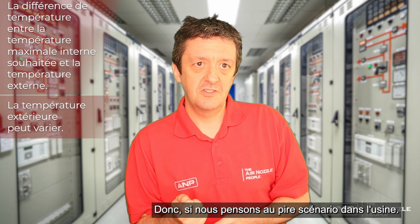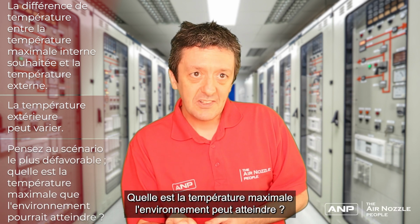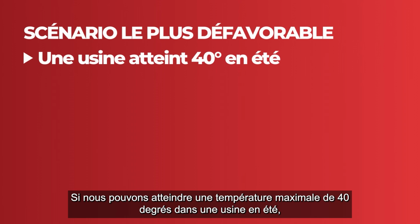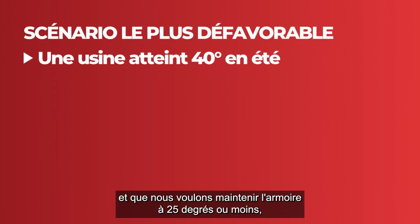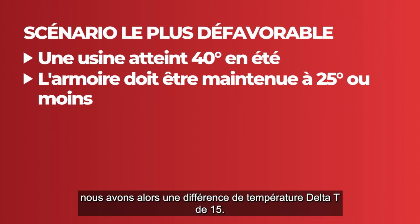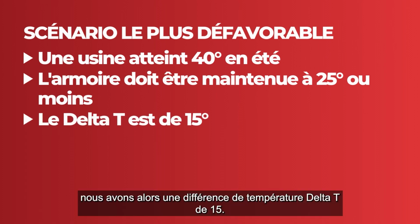So we think about the worst case scenario in the factory, what's the maximum temperature the ambient can get up to. If it can get up to a maximum of 40 degrees in a factory in the summer and we want to maintain the cabinet at 25 degrees or lower, then we have a delta T, a temperature difference, of 15.